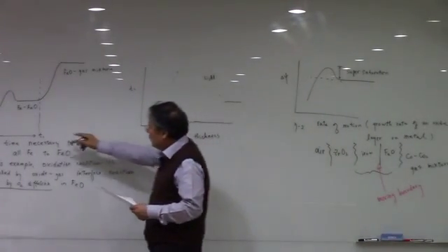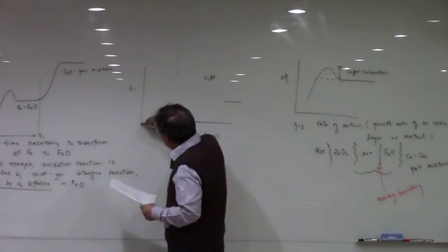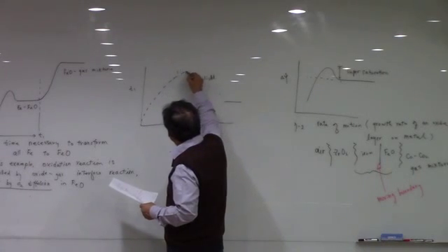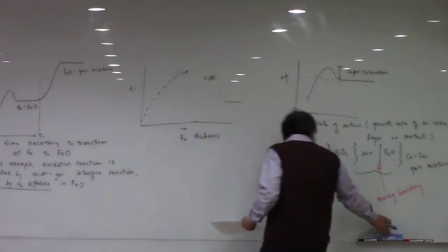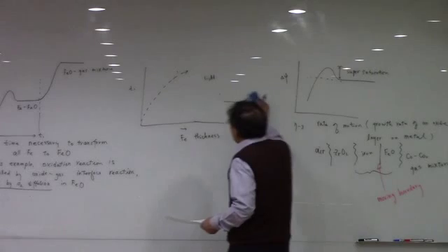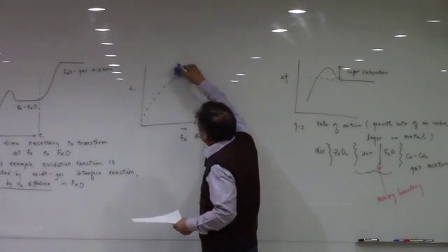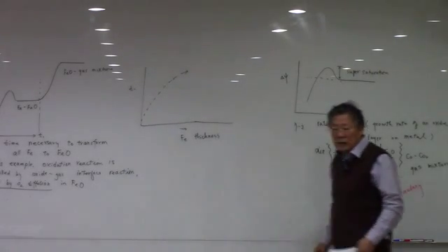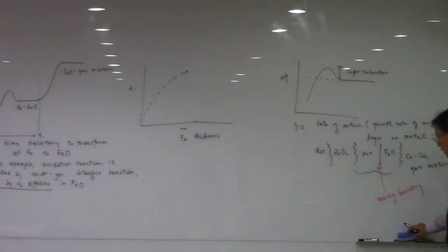And then you measure the T1 time there, then you might have some curve like this, and then you can solve the moving boundary problem. With this, you can see the velocity of this moving boundary in the iron and FeO. Then you can have kinetic data out of that.